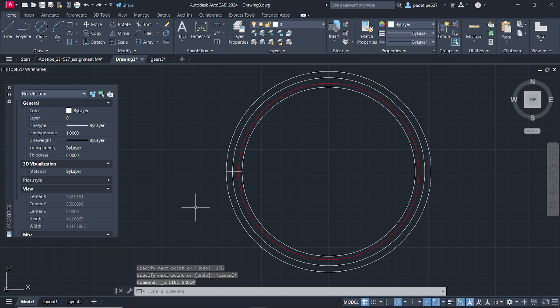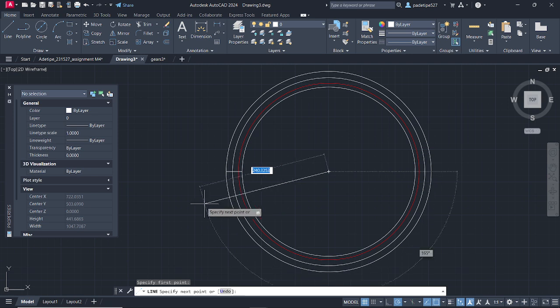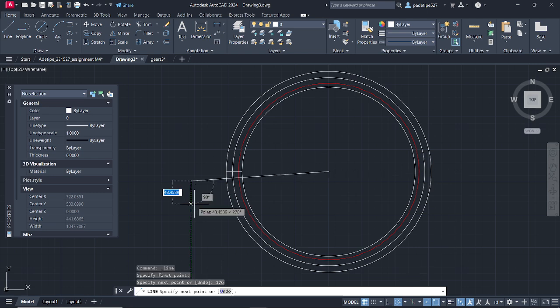Sorry, that was a mistake. What you can just do is simple. You come here, put it on the body so that this point will come out. Then the length, remember, can be anything, so you press tab. Your tab will shift this blue marker to the other side where you have your angles. Then you can type 176 degrees, then enter. So you have your line.